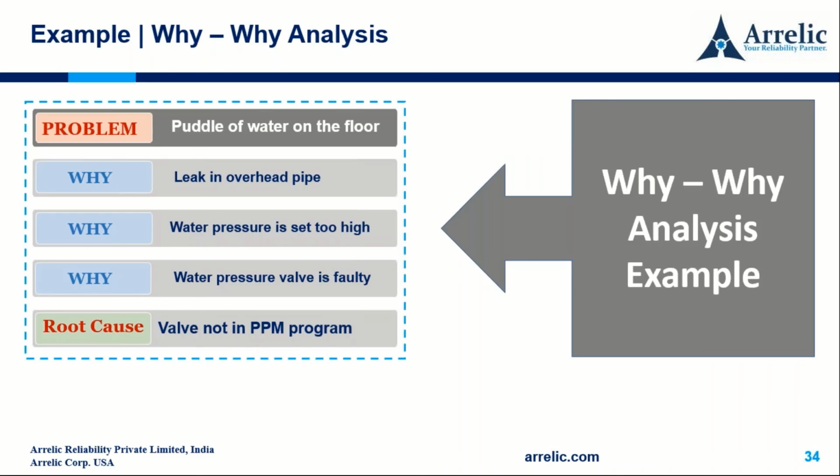So example, why-why analysis. Puddle of water on the floor. Why? Leak in overhead pipe. Why is there a leak in the overhead pipe? Because the water pressure is set too high. Why was it set too high? Because the water pressure valve is faulty. So valve not in the preventive program. So fix the issue by including the checking of the valve in the preventive maintenance program in order to solve the root cause and avoid the reoccurrence of the problem.